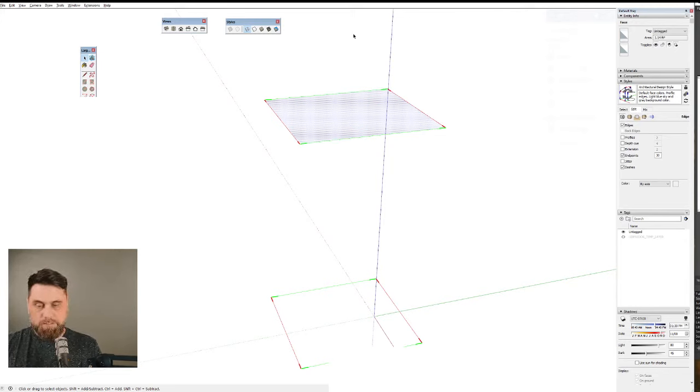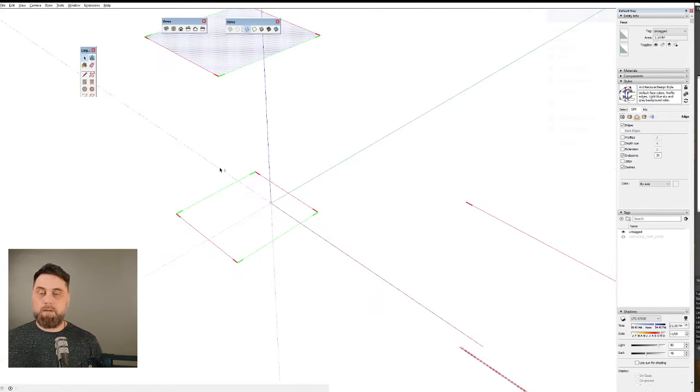Now it's important to understand why things happen the way they are. What are the rules? What is the logic? What things are we trying to understand and adhere to as we're creating our 3D model? Okay, so the concept of coplanar isn't just on the Z plane. If you think about 2D, when you talk about AutoCAD and Dynascape and you're drawing in 2D, that's generally called a Cartesian coordinate system. So it's the X and the Y, and in SketchUp terms, it's the green and the red. However, SketchUp is 3D software, so now we don't just have an X and a Y, we introduce the Z.